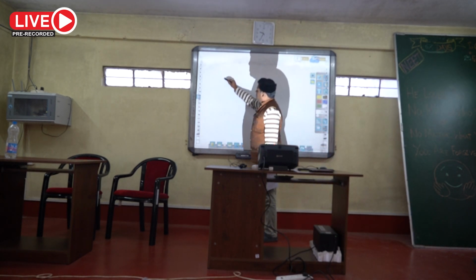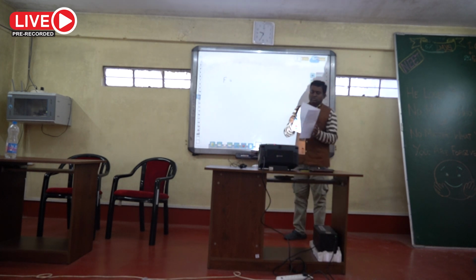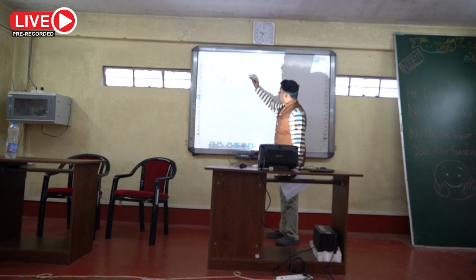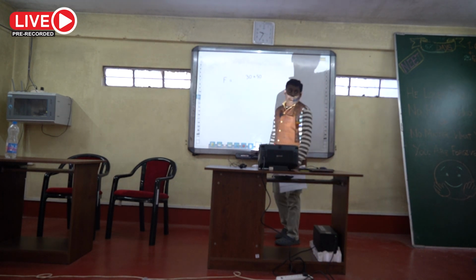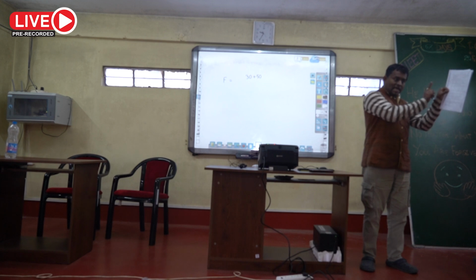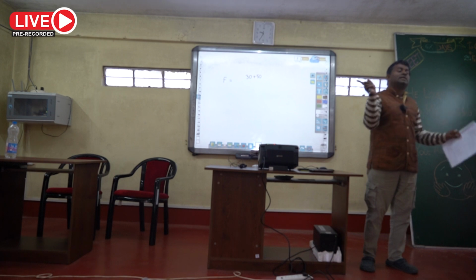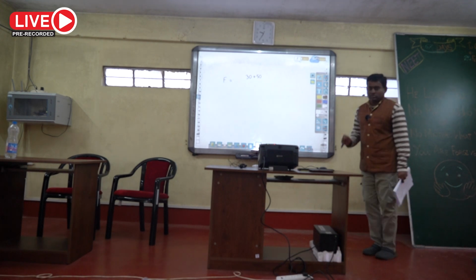See, the force that we want to calculate is equal to the change in momentum. So final momentum, final velocity is given 30 and initial velocity is given 50. So it will be 30 plus 50, not 30 minus 50. V minus u, because bullets are striking like this and then they are going back. So if initial velocity is in this direction, the second time velocity changes. So minus of minus u, that is plus u.